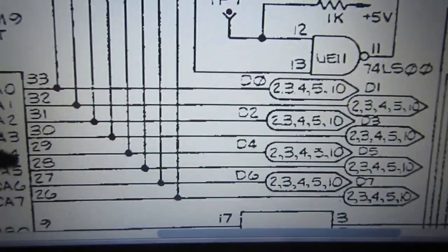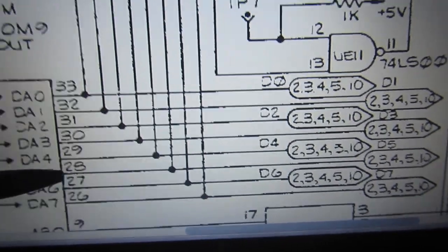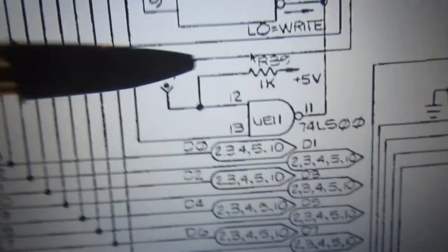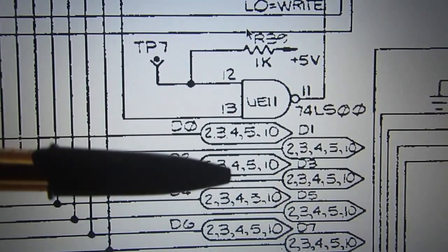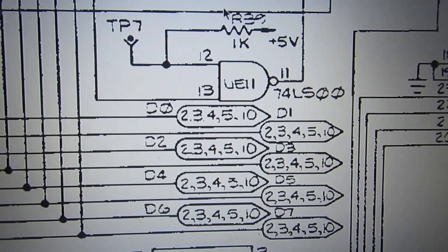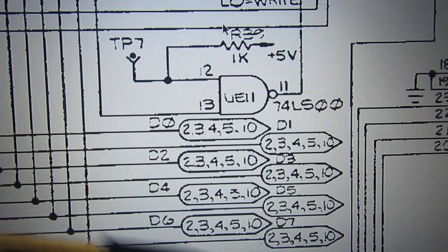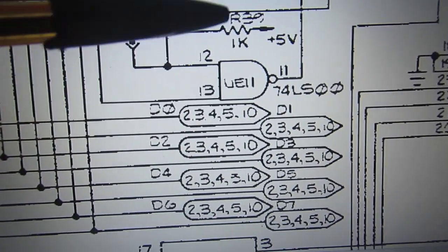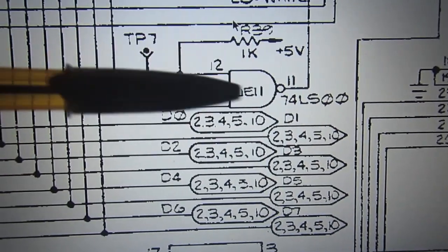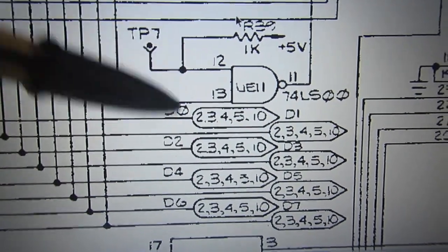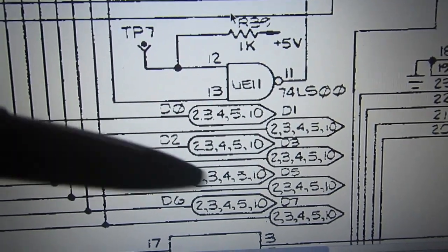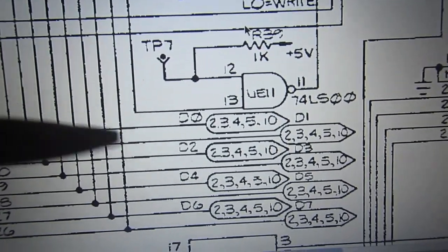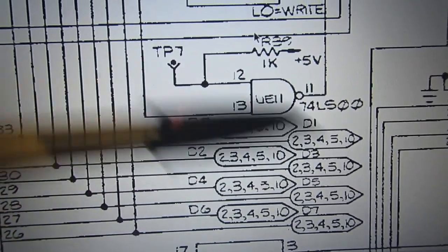So almost everything is directly connected to the CPU data bus without any transceiver in the middle. This is unlike the older PET revision, where the RAM at least had its own data bus transceivers. So on an older PET revision, a fault like this was more tied to RAM access and not any I/O, video RAM and everything, like in this case.